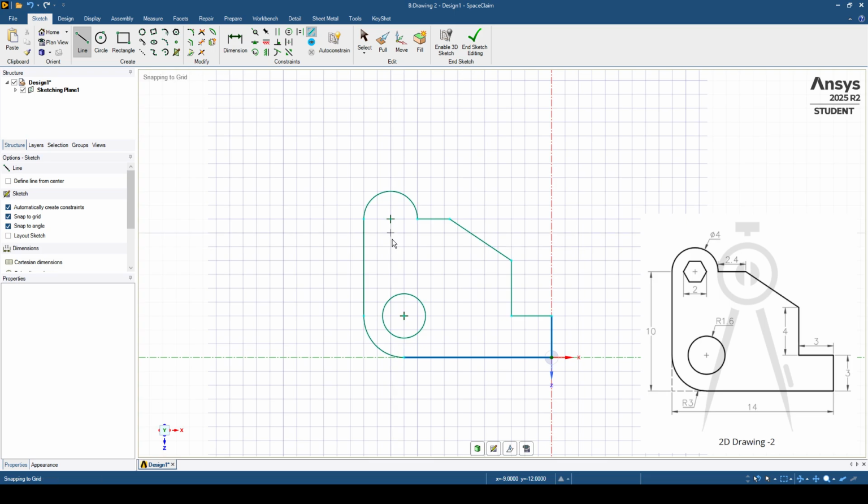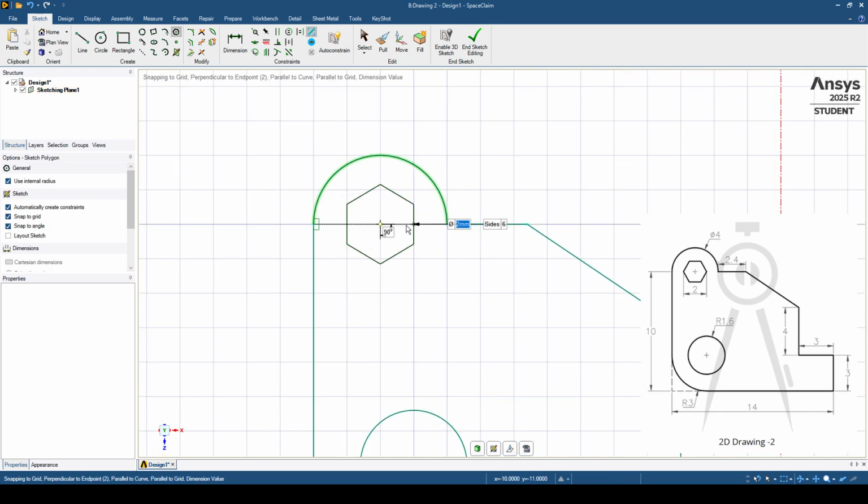So to do this, in ANSYS there is a Create tab above, and there is a polygon feature here, as you can see. You click on it, and without changing anything in the settings, if you go to the center here, we are looking to do it with a width of 2 millimeters. As you can see, if we do it with 2 millimeters, it's not as we want.